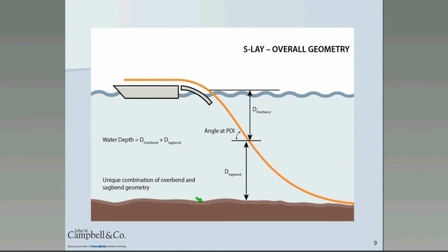So that difference in elevation change is very important in terms of how much curvature is required to get the pipe off of the supports alongside the ditch onshore and into the bottom of the trench. And as a result, the radii of curvature are very, very large. And because they're very large radii of curvature, the bending stresses are very, very small. It's very rare on an onshore pipeline construction that you would have any issues in terms of the bending stresses related to the lowering-in of the pipe into the trench.